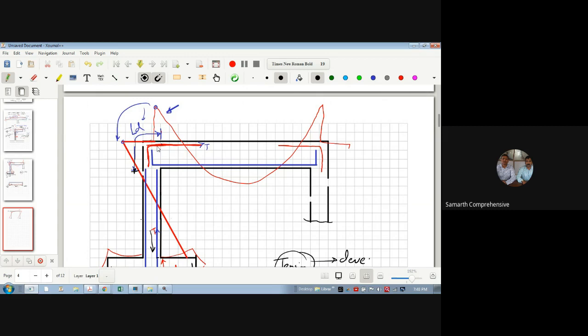So on site I generally recommend giving the instruction to them. As far as the beams are supporting on columns, provide LD for both the bars, just to avoid the confusion, because site people are laymen and they don't understand the philosophy of design. So if you feel that they will make a mistake or error, please don't allow them to think. They need to follow the drawings only. They will not think about where the tension is in the beam or in the column. So better we give this instruction. Structurally it is no problem. It is good for earthquake also. Okay. Any question? No, sir.